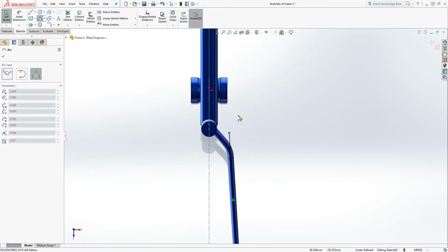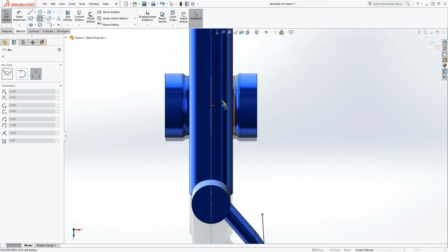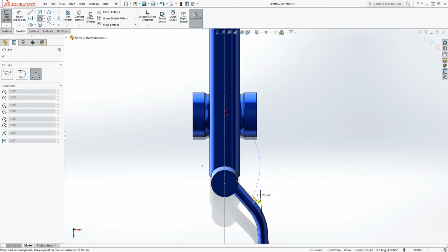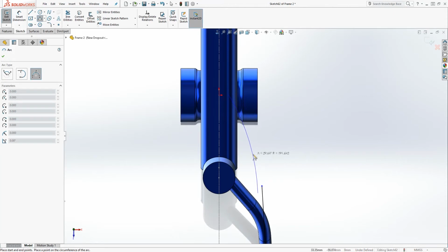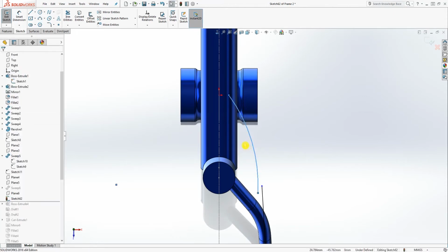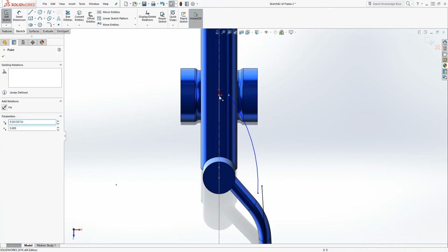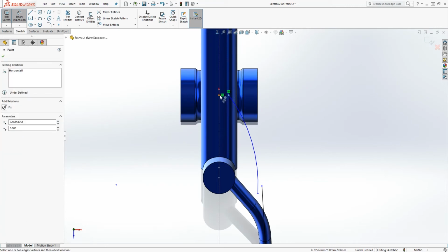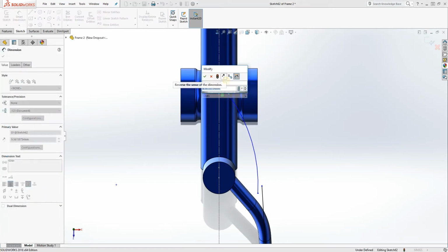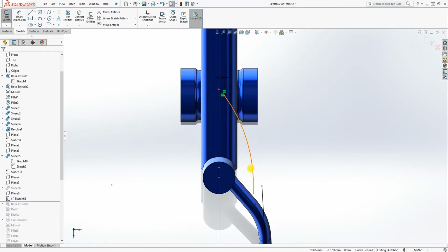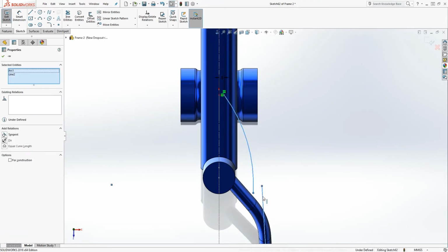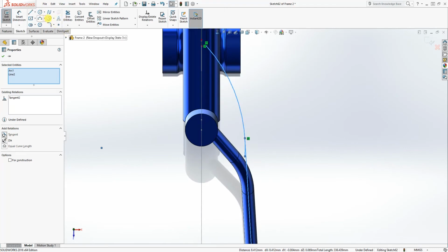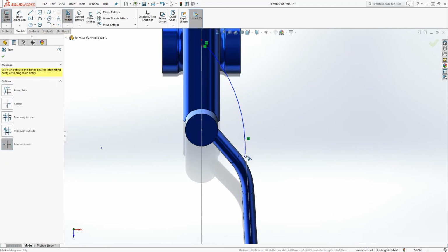I'm going to draw an arc with a point over there, starting over there and ending somewhere over here, and drag it out like so. The point of this arc and the origin point are going to be horizontal to each other, and the dimension between them is going to be 5. Select this arc and that line and make them tangent, and trim that off.